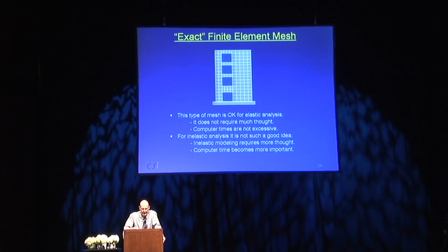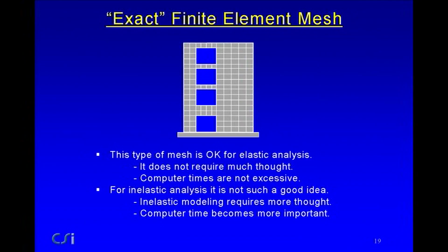Now, for inelastic analysis, this isn't such a good idea. Inelastic modeling requires a lot more thought. It's okay if you're doing elastic analysis. There's lots of elements, we don't have to think about it. Nonlinear analysis, you'd better think about it. It's not a matter of just using more elements. And also, computer time becomes more important.